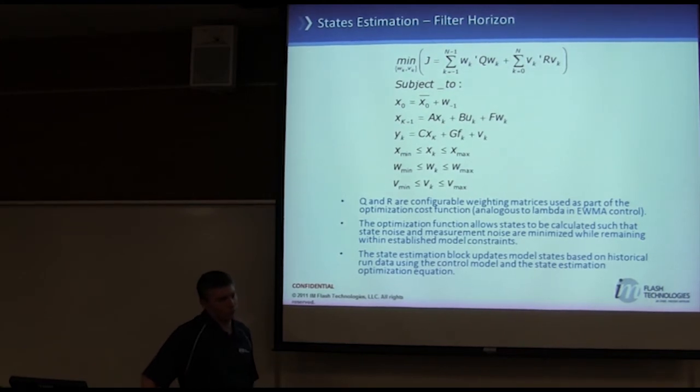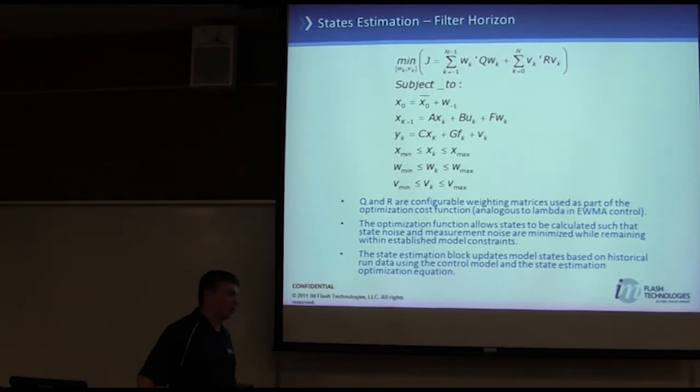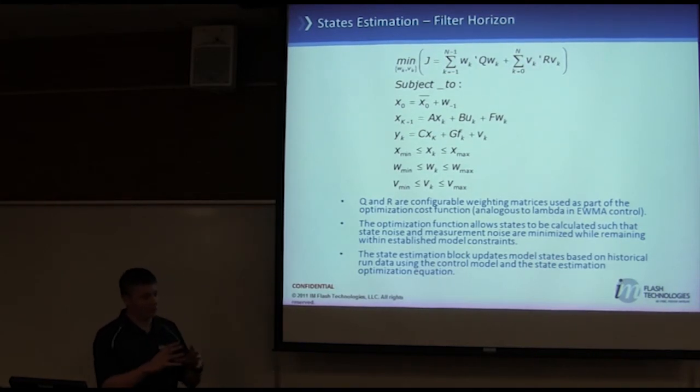What does it mean when you say state space? It just means that you define states of your system, and they're either measurable or immeasurable. With those states, you can define how your system's behaving at any snapshot in time. If you know the states of the system, you can tell how it's behaving. So you can identify parameters that are key indicators of how the system is behaving.